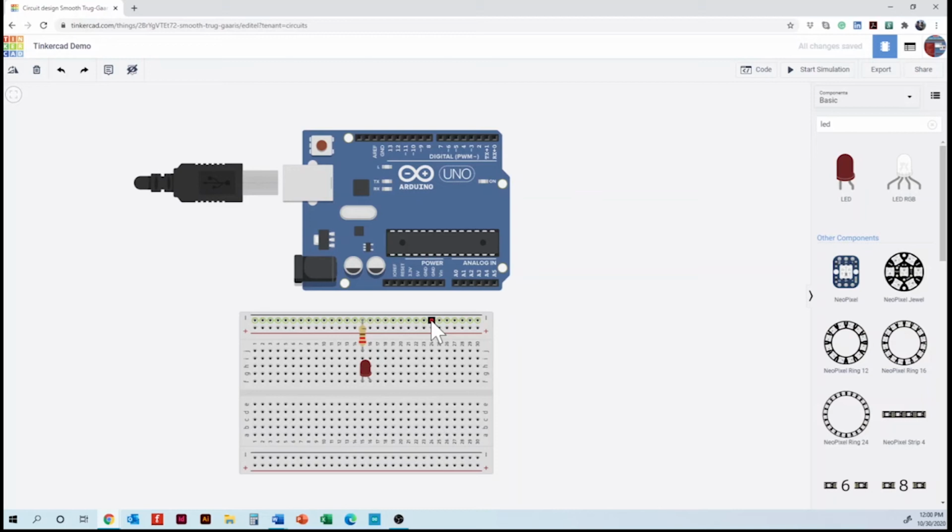And in here we must have ground and 5 volts to create that loop and putting the energy to circulate. So that's why the microcontroller has the grounds and the 5 volts. So if you see in here, we have the two connections, ground and 5 volts. So 5 volts is gonna be always connected to the positive side of the breadboard.